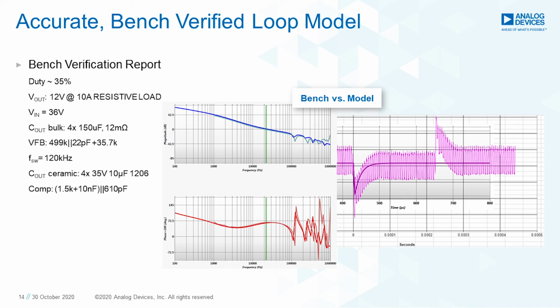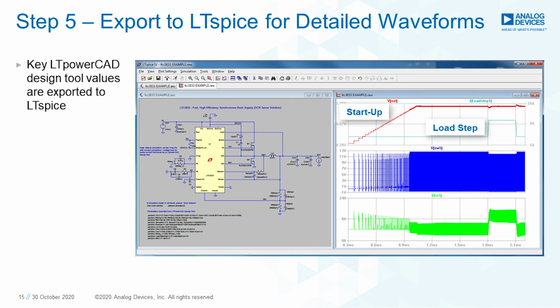The next step is to export the design to LTSpice for a detailed time domain simulation of important performance metrics, such as startup behavior and load step response. All the important component parasitic values are exported with the schematic to ensure accurate simulation results.